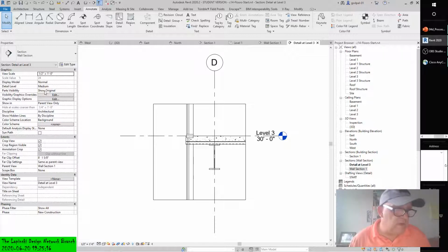If you define the boundary line at the center line of the supporting member, define the cantilever value for the steel to be 0, or 0 millimeters, and concrete to be the value appropriate to your engineered design. Sometimes these values may need to be negative distances to achieve the desired cantilever condition. When you finish the sketch and observe the slab edges in the section view, you will see a more accurate representation of the appropriate construction technique for the floor element.